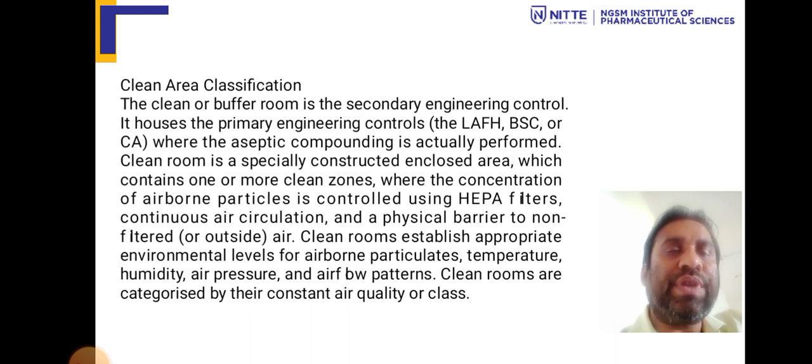So, clean area classification. The clean or buffer room is the secondary engineering control. It houses the primary engineering control like laminar airflow, BSC, CACI, where aseptic compounding is actually performed. Now, a clean room is a specially constructed enclosed area which contains one or more clean zones where the concentration of airborne particles is controlled using HEPA filters, continuous air circulation, and a physical barrier to non-filtered or outside air.